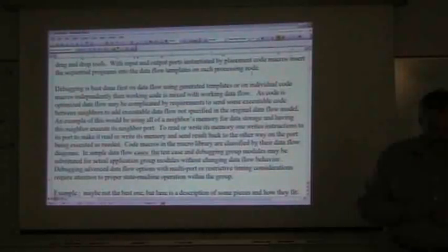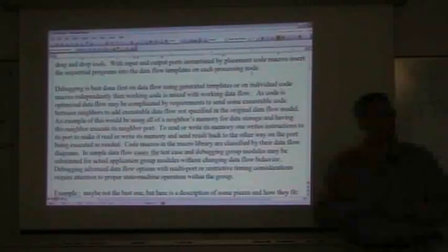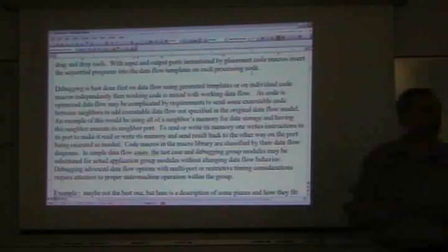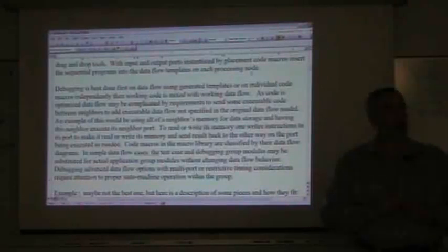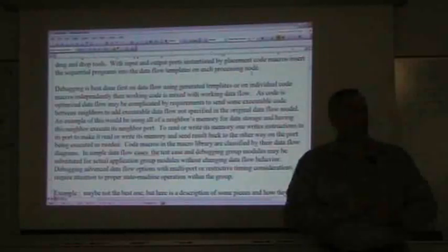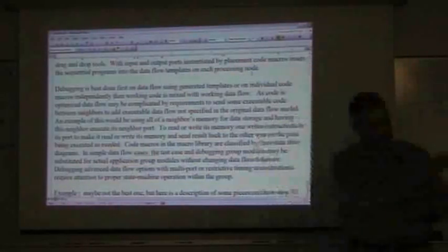I looked in an example of programming microprocessors and saw this was one of the simple, trivial examples they use to train people: write pulse width modulation and write an SPI driver. And so what I did was, we have a node that boots up in SPI. It is connected to an SPI flash. It has ROM code to boot packets from that SPI. So I put some code in that node's RAM to call some of that code to read data packets from the SPI flash and send them out.